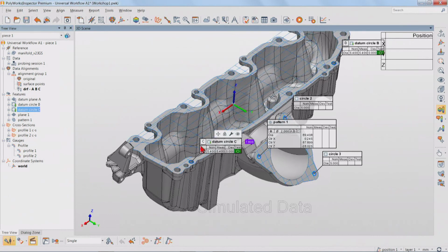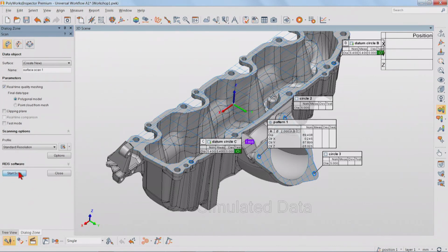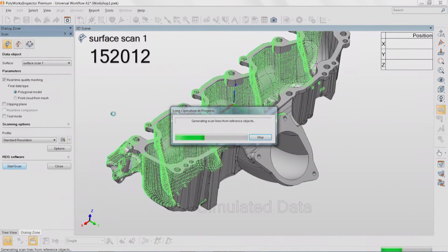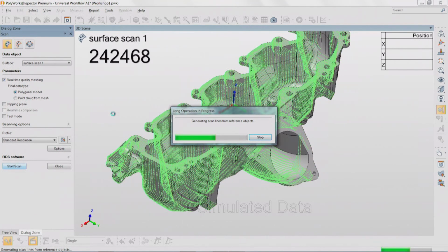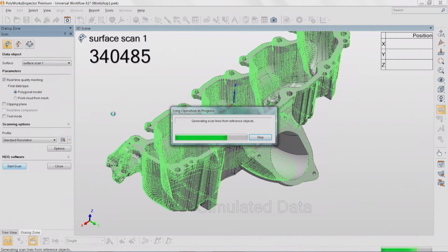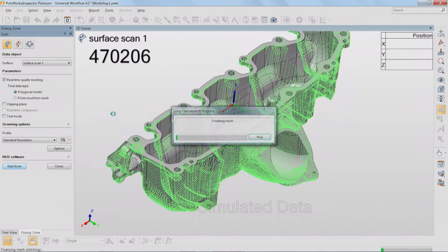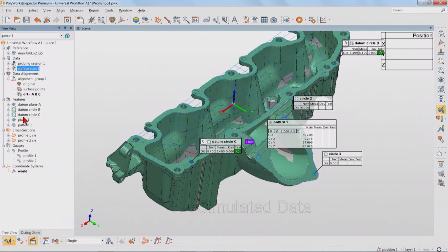Now at this point, I would like to make sure the remaining measurements are extracted from scan data. So the offline simulation mode also allows you to gather all the data you need by simulating data from the CAD model surface. Right now, this would be extremely useful if I had to do a best fit, if I had to do a color map ahead of time, or, like in my case, have the capability of extracting all my measurement objects on that data and making sure I can record all the measurement parameters necessary for the extraction. So it's about to be done. And once this is completed, this is where I will simply go extract on the remaining measurement objects, namely all the flange features and the profile gauge that I want to measure.